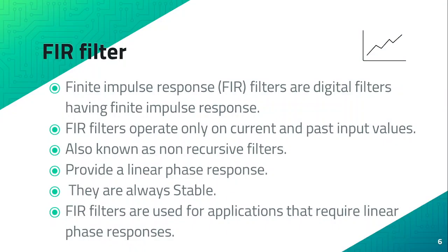Next is the FIR filter. FIR stands for finite impulse response; these are digital filters that have a finite impulse response. FIR filters operate only on current and past input values and are the simplest filters to design. They are also known as non-recursive filters. FIR filters provide a linear phase response. They are always stable because they are implemented using an all-zero transfer function. They are used for applications that require linear phase responses, like high quality audio systems.